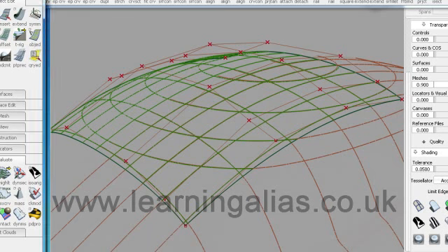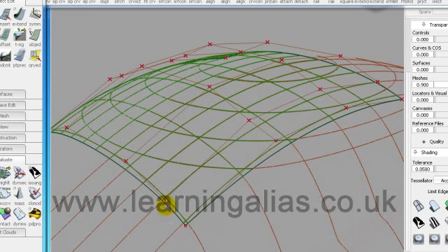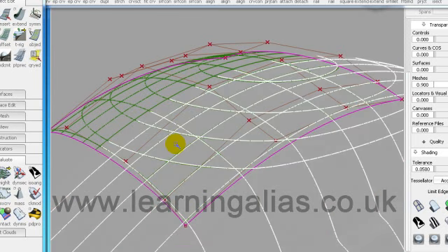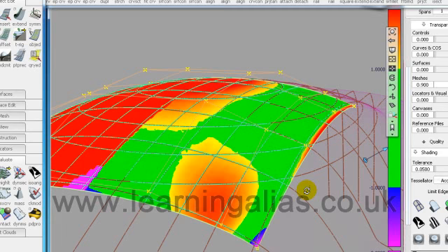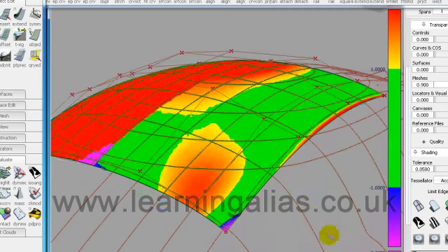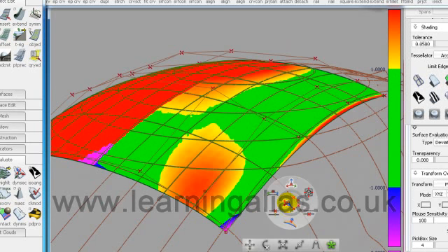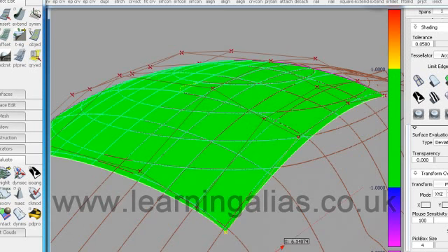Now let's go over to the deviation map, set it up to acceptable distance 1 and ramp distance 2, and you see that we are very close. Okay, so blue means we've got to go up, and red means we've got to go down. So let's pick CV and NUV this time. Maybe I'll move in XYZ so that I don't distort my boundaries. Let's try that. I think that's a better idea.